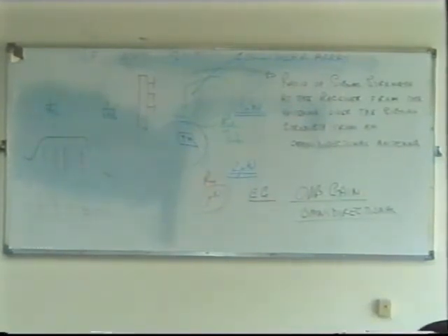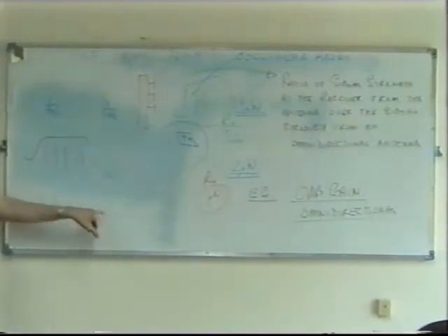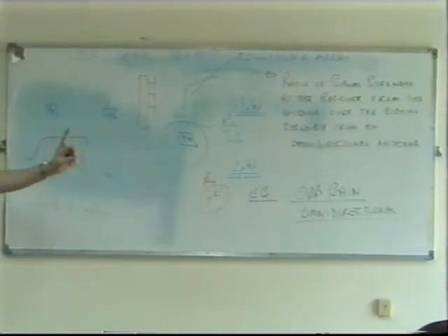No, we have in the airport. Yeah, but in the airport, in that example you chose HF as an example. Yeah. And we do actually do that, but we use a log periodic antenna, which looks a little bit like a Yagi when I draw it on the board here, but in fact each one of these elements are active elements, and very basically, you can say each one of these elements is tuned to a different frequency within the HF band. How to make it active, all of these? Just connect them all to the transmitter.